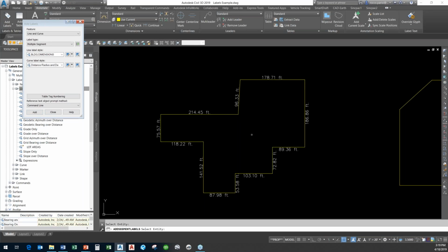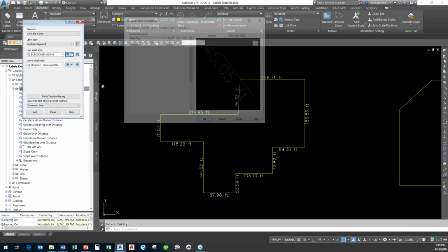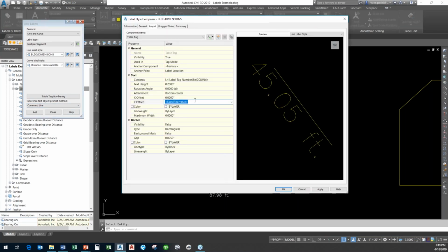And again, you may look at it and go, oh, you know, Jim, that's kind of okay, but it's on the outside. That's all just about formatting, right? I can easily go back in, modify that, and say, look, see right now it's doing a Y offset of 0.025. I can set that for a negative 0.03. I want a little bit more space, okay?